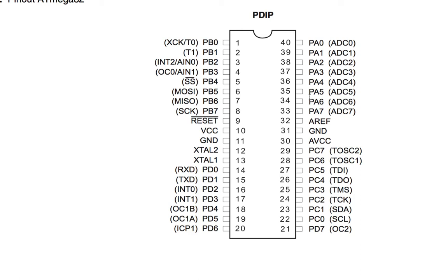Sometimes even if you didn't declare it, it will still work, but the best practice is to declare it, especially if you're handling higher voltages. Then the second thing that you need to do is to enable the ADC bit, which we basically call ADCSRA.